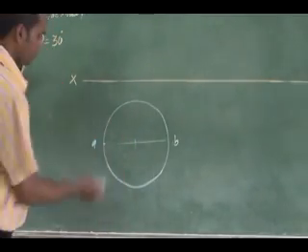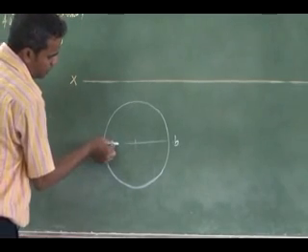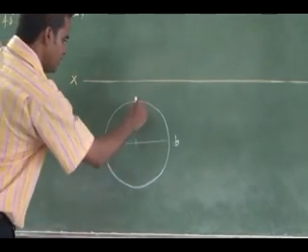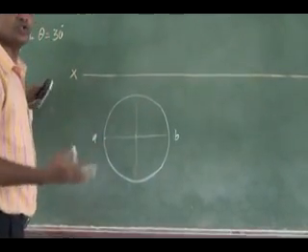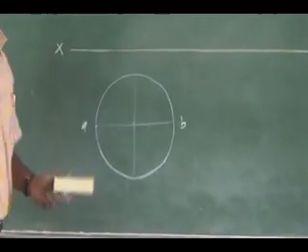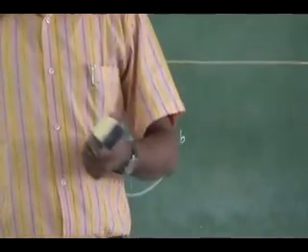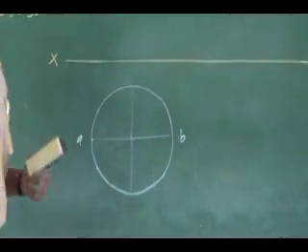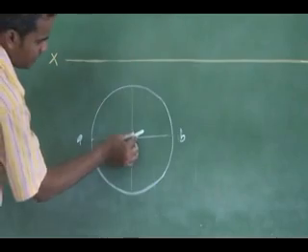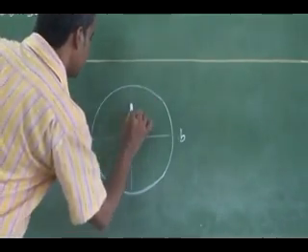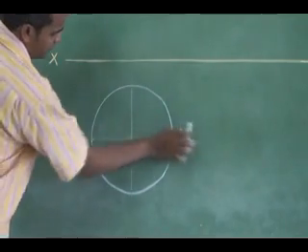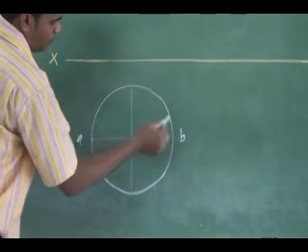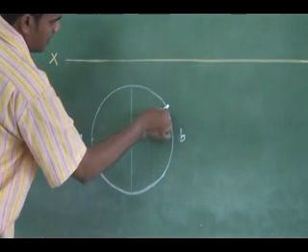If you have a circle that you have to divide into 12 equal divisions, how can I divide it into 12 equal divisions, you know. Using your drafter two settings, 30, 60 degree, I can divide it. Carefully you divide it. While dividing this circle, look for the error also and carefully add it in your drafter. Otherwise it won't match. So divide.